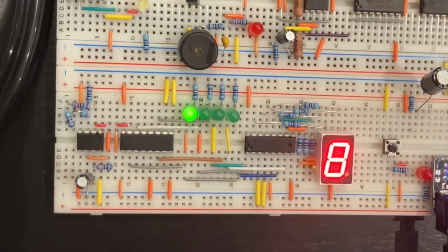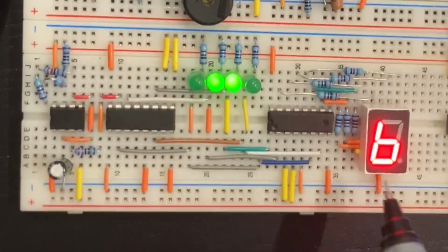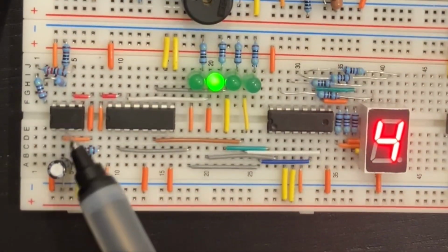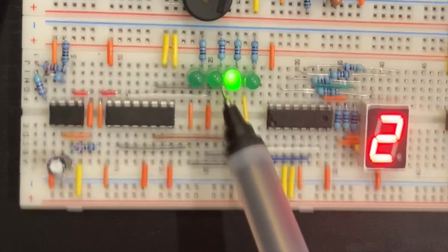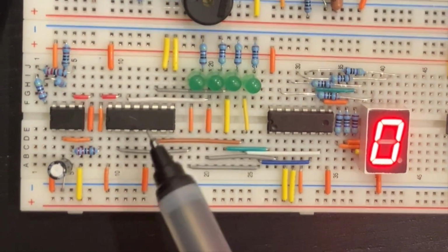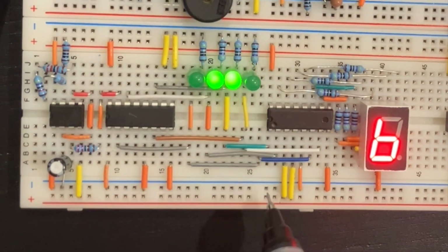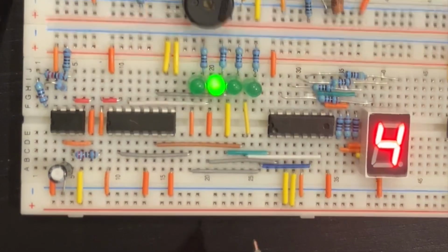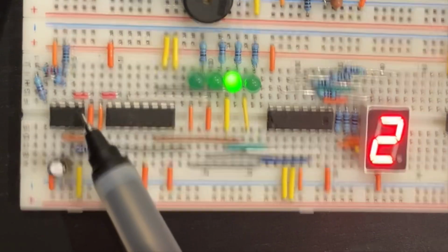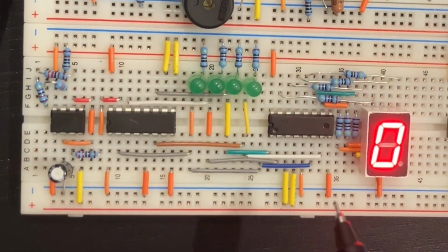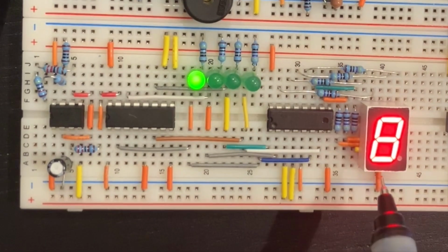This binary and decimal countdown circuit simply takes the 555 oscillator's output and uses it as a clock signal, for which each high-low cycle adds to the count by 1. A 4511 converter is used, which takes the binary output from the 4510 and converts it into decimal using the 7-segment display. The benefit here of the 555 is using external components.